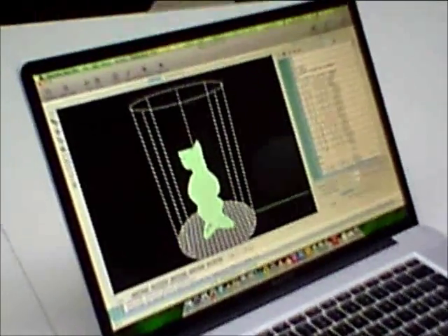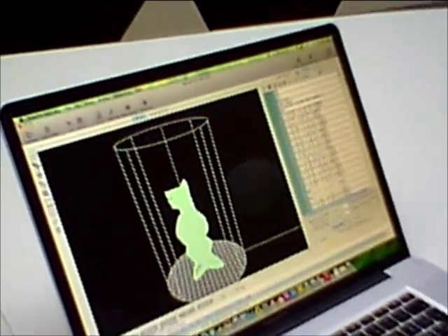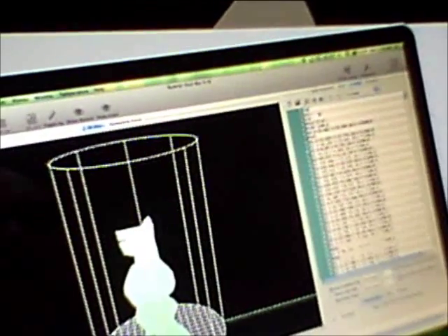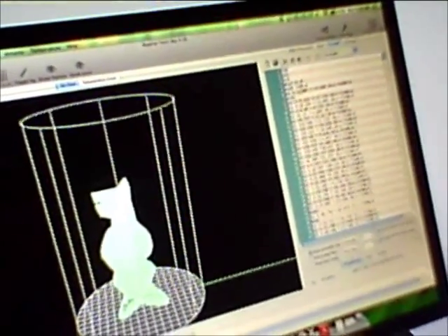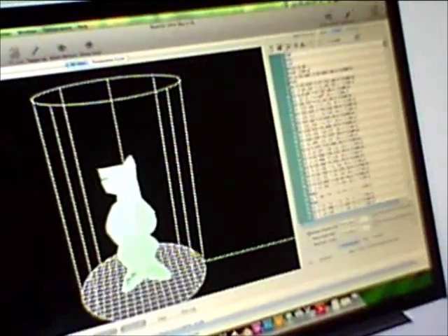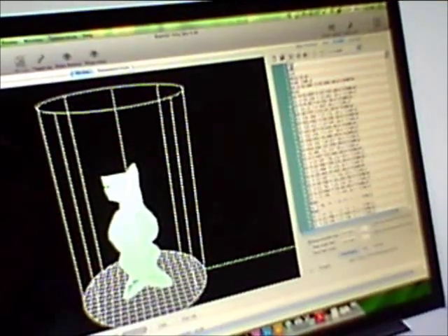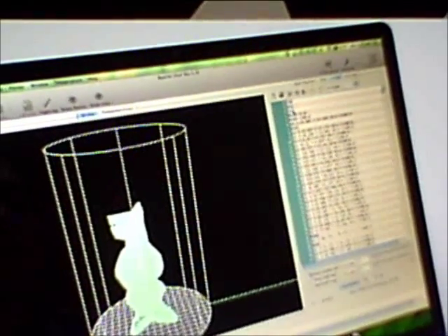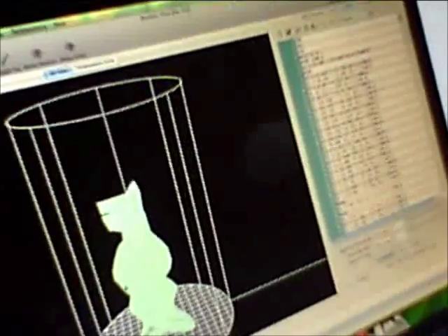It's now been sliced, and you can see on these tabs it's moved from object placement over to slicer and now into G-code. So we started with the STL file. It's now been sliced into a G-code file, and G-code is the kind of language that the printer manages to speak. You can see here G90 is actually the measurements, G28 sets the printer to the home position, and then these are actually all the points on each slice, the X and Y points.